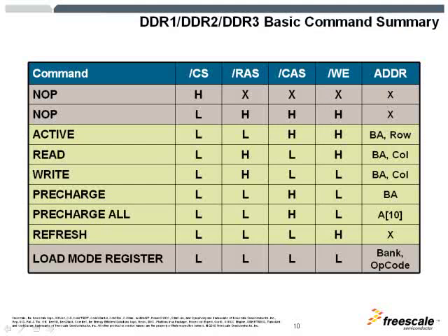In an active command, we want to open a row. So we select the chip select that we want to access, and the row access select is pulled low to indicate that we are going to select a row from the memory.